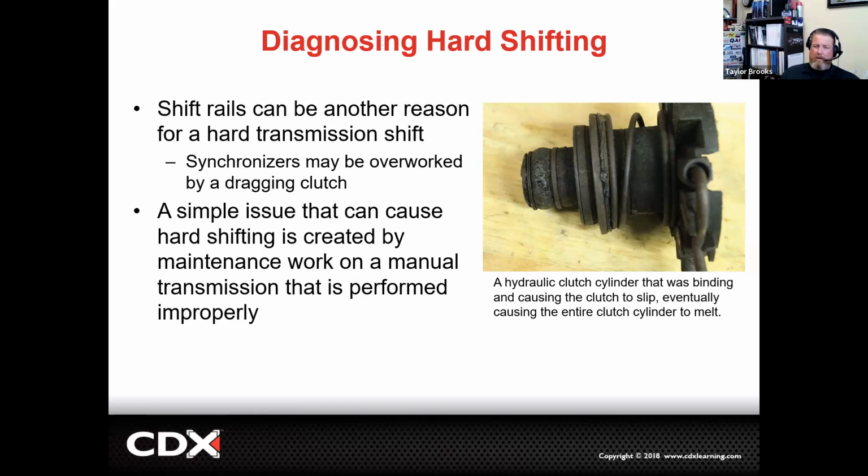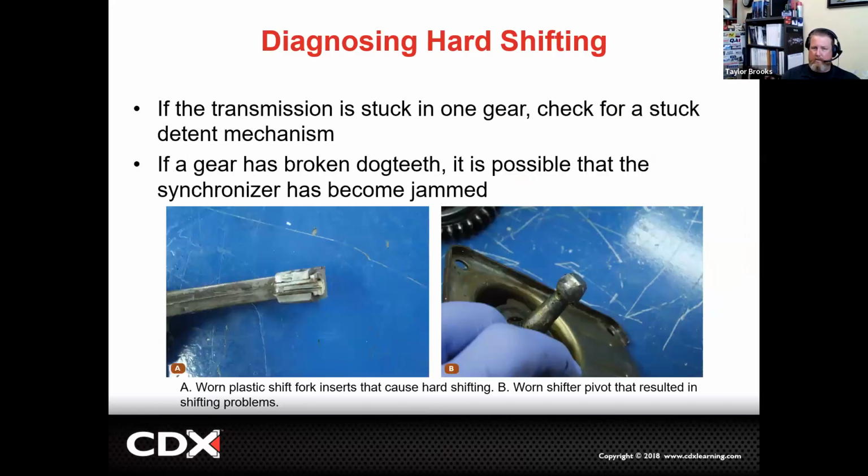We can also have a slightly leaking clutch actuation solenoid for our throwout bearing, and that has caused the gears to drag over time, and that over time will cause us to have an improperly shifting transmission and for it to wear out.